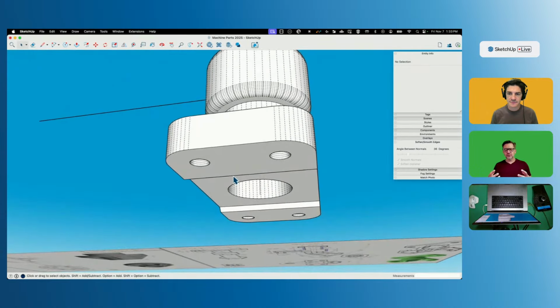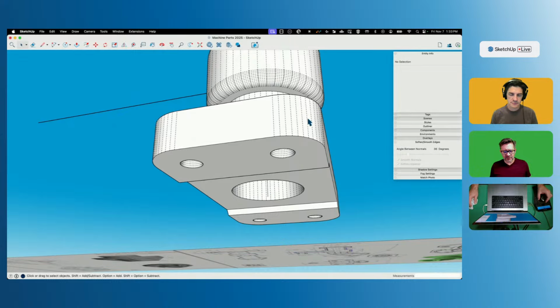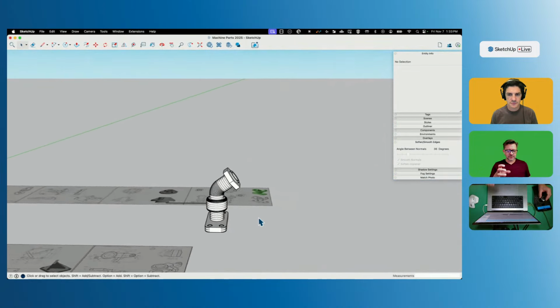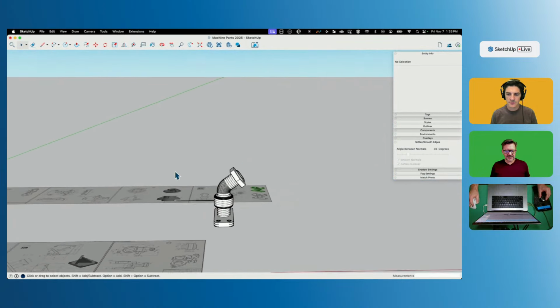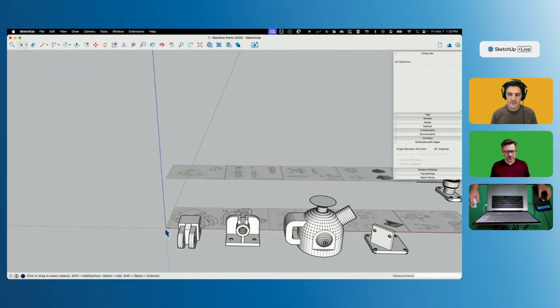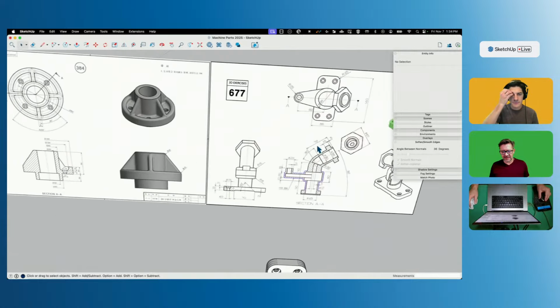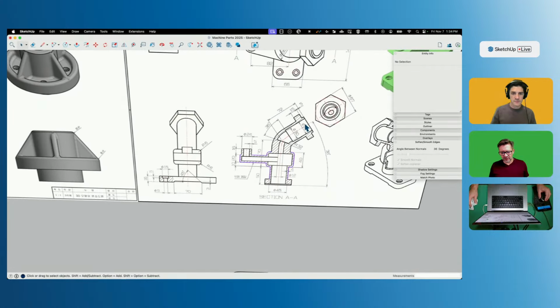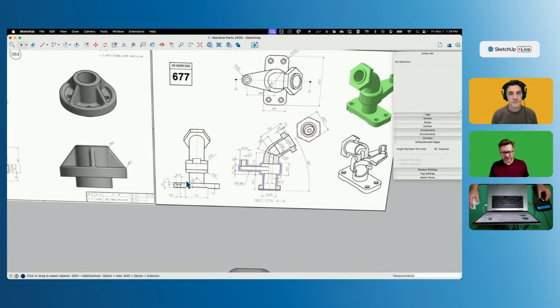One of the things I was talking about earlier was, circles break, stuff moves. When you push pull, a lot of times you lose where the middle of a circle is. That happens. So when I model stuff that's based off of a central point like this, a lot of times I'll model it on the axes. So I'll model it right here, so I can always go back and pull a dimension, because you can see how many dimensions they pull off of the center here.